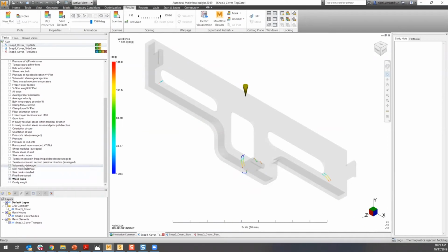Now, another thing, and I didn't talk about this previously, but typically what happens with any injection molded product is since you have a high temperature and molten material at the beginning, and then that's solidified at the end of the process, you are likely to see some shrinkage in the part because materials shrink as they're cooled. So usually you're designing your mold to a volume at a certain size that is higher than the actual part size.